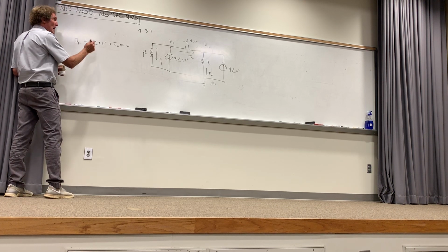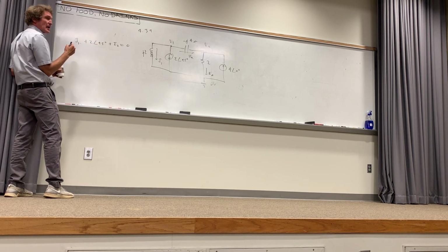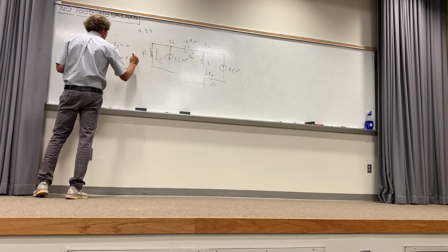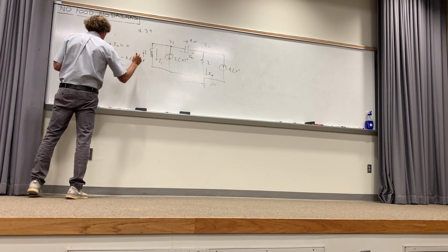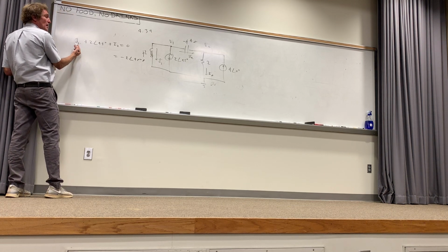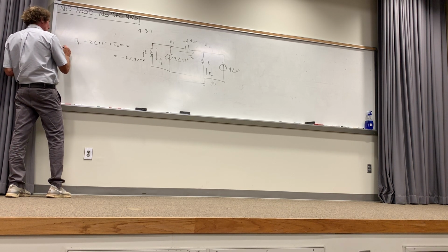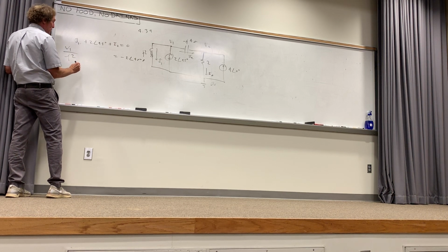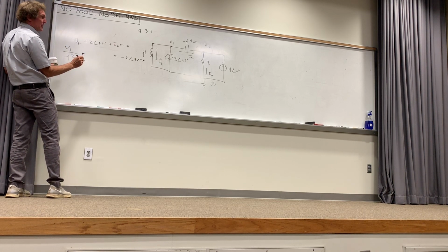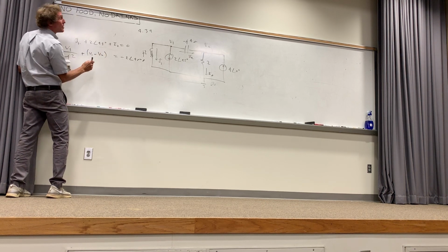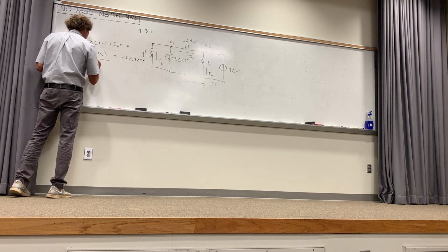Over here, I'm going to take this to the other side, 2 at an angle of 45, okay? So that becomes minus 2 at an angle of 45 degrees, amps. Now, I1 here, what is I1 going to be by my designations? V1 over J2. Plus I2, what is I2 going to be? V1 minus V2, over negative J4. Minus J4.